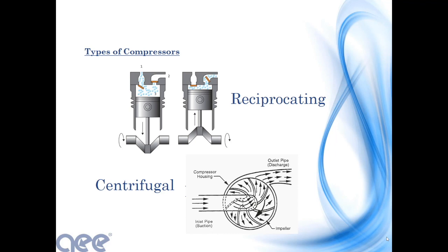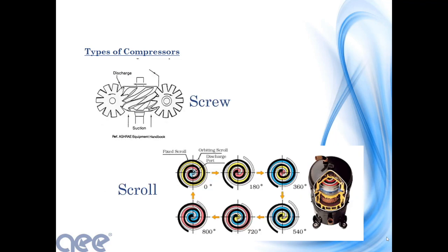So when you hear references to suction pressure and temperature, and discharge pressure and temperature, that's just each side of your compressor. A screw compressor is a different technology where you essentially have three gears, or two gears and a screw. The suction side pulls in the refrigerant gas. In between the gears, the refrigerant gets compressed into a high temperature, high pressure gas, and then gets discharged out to the condenser. I don't remember exactly when the first screw chiller was designed, but it's more mechanically efficient and uses less energy input for a given pressure and temperature increase for refrigerant than the centrifugal chiller.